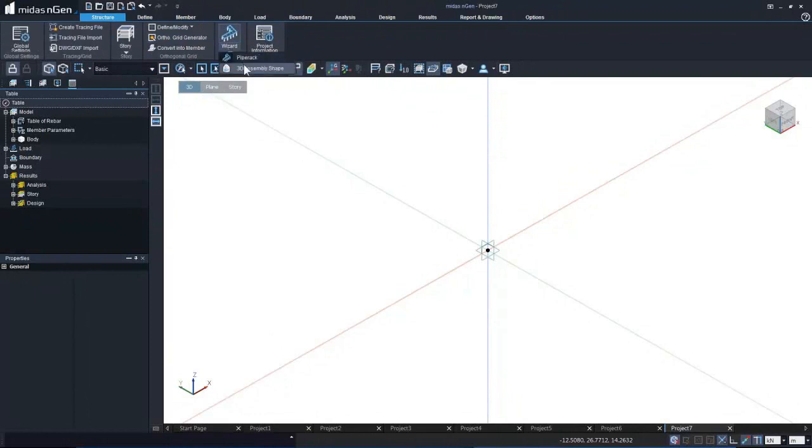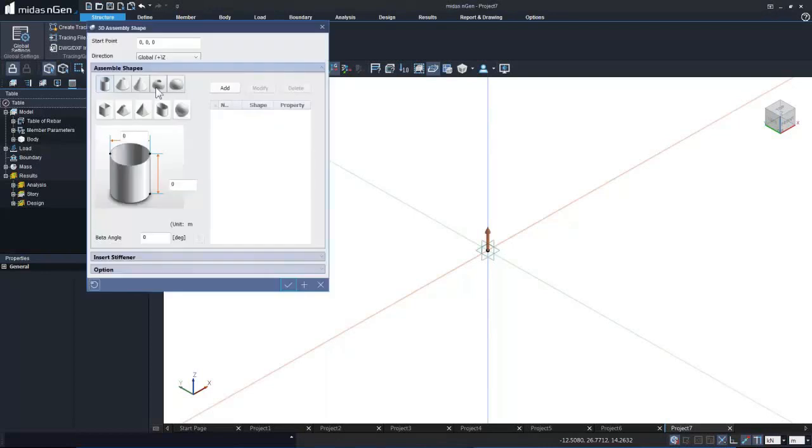So in this wizard, we have got the 3D assembly shape, which has various numbers of predefined shapes. There is a cylindrical one, and we have conical ones, and dome-shaped, and there is box-shaped, and so on. So what we will do today is we will use this box shape for our box culvert and provide the information. So I would say this would be the height or length. So our box is actually going to be horizontal. We will change the angle later on. So let's simply provide the distances.